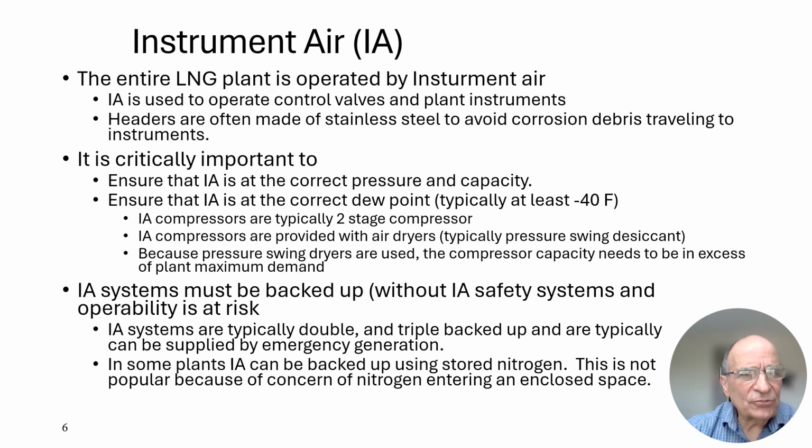Instrument air is extremely important for your plant operation. The entire LNG plant is operated on instrument air. The instrument air moves valves and controls the instruments that allow the valves to open the amount that needs to be opened. Without instrument air, the plant cannot operate.